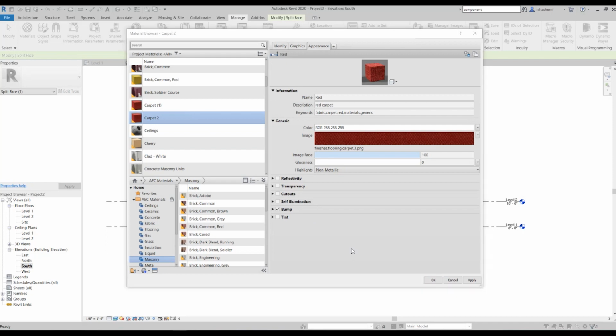The next step, which is the very next thing you should do, is duplicating the asset from here. This is very important. Just write this down and circle it. Otherwise, you will encounter a mess in your project. To duplicate an asset, you need to click on this double paper button at the top. You just need to click on it. You may not see what has changed here except this little number 1. So let's explain what happens when you do this, and this is very important.